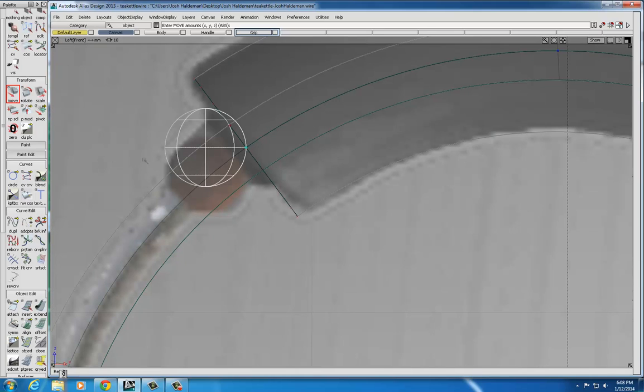Now when I go back to the front view, you can see the only thing I have to do is just rotate it down so it lines up. I'm going to do that by using the Rotate tool. And which axis do I want to rotate around? Look at your navigation helpers in the corner. Notice you can see the Z and the X, which means that the one that we want to rotate about is the Y, the one we can't see. So that'll be the middle mouse button. And we just want to click and hold.